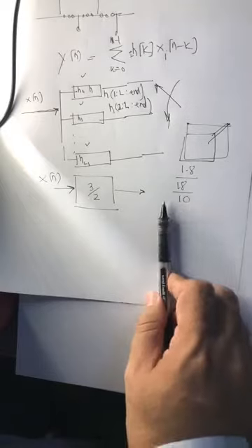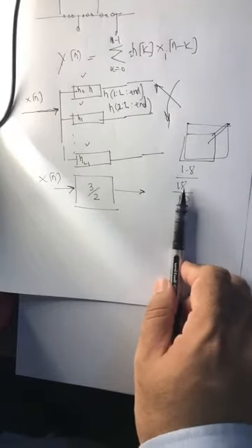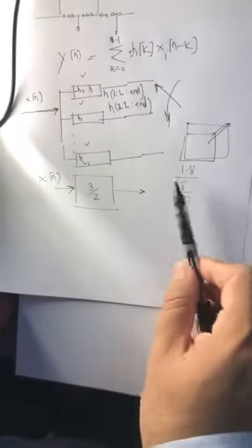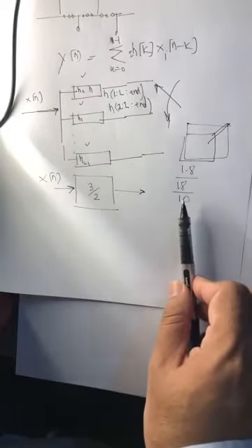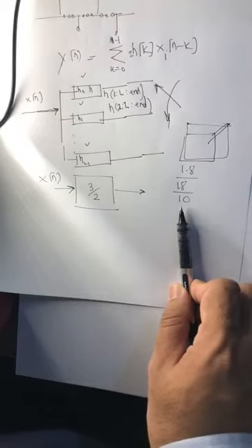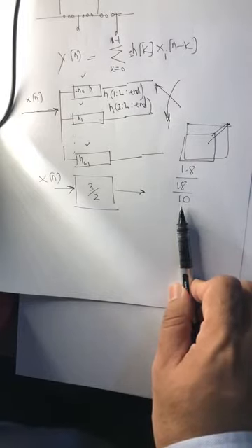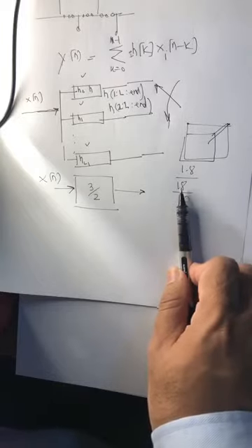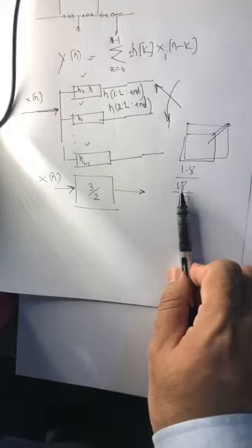The only way is, first you increase the sampling rate by a factor of 18, and then reduce the sampling rate by a factor of 10. So it has to be done in 2 steps. Always we do the interpolation first, because interpolation will not reduce the amount of information.